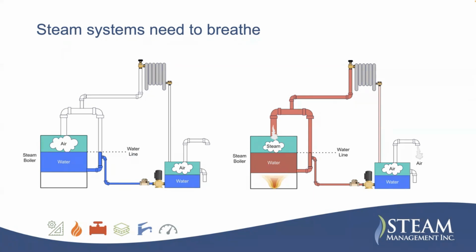And that's why we saw that boiler feed tank or the condensate tank that exploded and turned into a bomb. When you look at a steam system, when it's cold, it's filled with air. Most of it, 90% of it, is filled with air. The only thing that has water is the boiler and maybe the water line in the condensate tank.